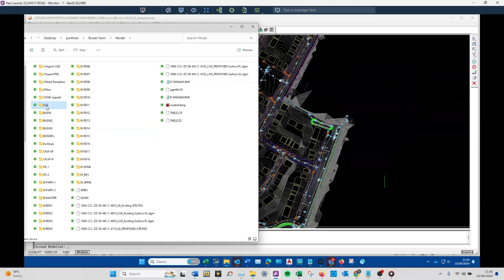So you have your DBU file. That's just to recap really quickly. You have your DBU file that sets the design units for your drawing. You have your PDS file that contains all the information to create your DGMs. Your DGM, that's the surface mesh, as if you're out there walking on it, whether it's the existing site or your proposed site. You have your buildup files that has all the different pavement, all the materials, as if you're the contractor ordering all the materials to build the site.